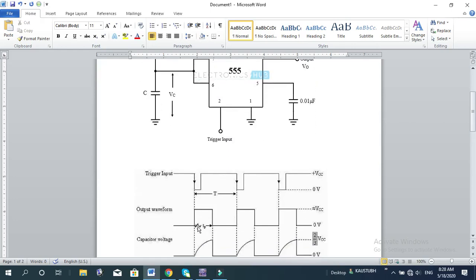So once the TP time gets finished, it goes low, and once it goes low, this is the stable state. It will remain stable, at the 0 state, until the next clock or next trigger appears. And when the next trigger appears here, the pulse is again forced to go high, and again it will remain high for TP, and so forth.